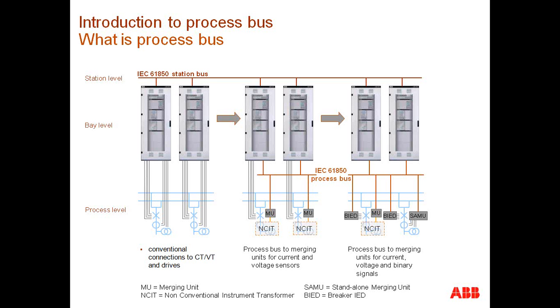The idea behind this concept is twofold. Number one, you are providing total isolation between the control house and the primary equipment. Okay, so things such as open CT circuits and issues with the isolation of VTs are addressed, and that is an issue inside the breaker cabinet, but it's not an issue inside the control house, since the signals are coming in the form of digital Ethernet packets via the communications network. That's one of the things. So safety is one of the elements that 9-2 addresses.